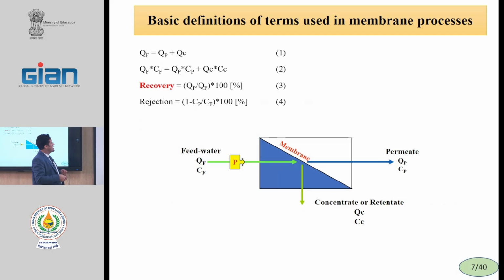Therefore, we do not have complete recovery. Based on the process, we usually have 75% recovery. Sometimes we can increase to 90% based on the feed concentration. If the solute concentration is low, we can increase the recovery ratio. Therefore, recovery shows how much product can be produced.